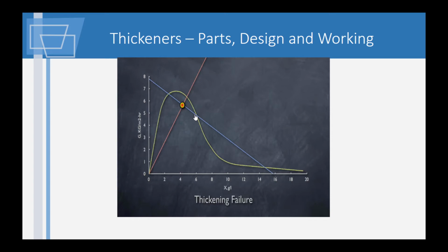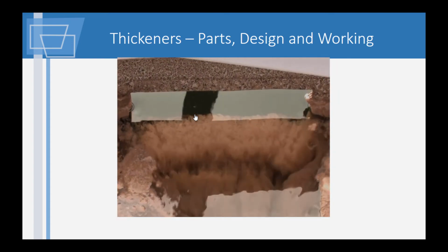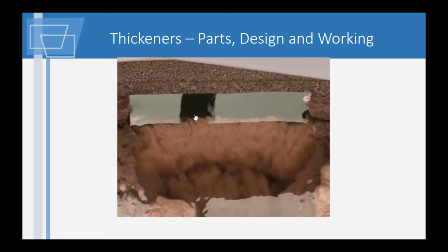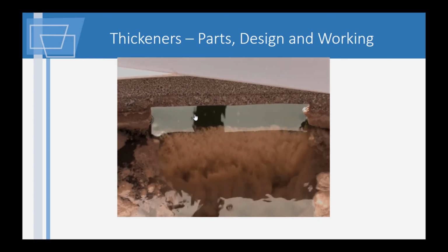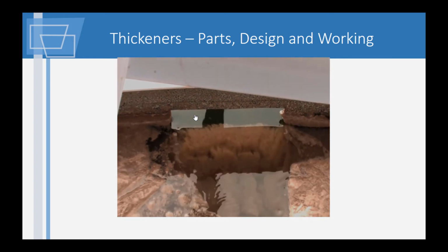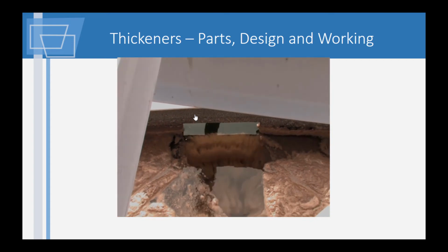How? Well, if solids are passing over the weir, the concentration of the system will decrease. And as we've already covered, a lower mixed liquor concentration will move the underflow line back towards the origin and eventually under the settling curve. The bad news is, if this happens, you probably just violated your permit. So the goal is to avoid either type of failure. Let's take a look at some real-world scenarios now, where the state point diagram can help you determine what actions you can take as an operator.